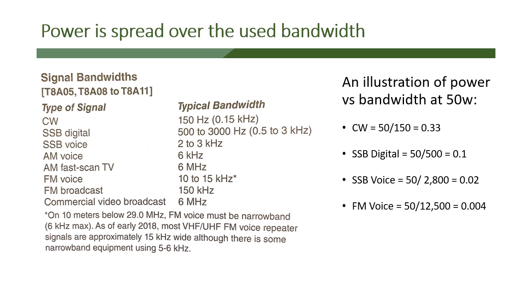Again, these are not the actual numbers, it's just an illustration to show you that as I spread the power, the number of watts I'm going to send out of the antenna, across a wider bandwidth, the average power across that is going to be lower. And that's why, to get the equivalency as the bandwidth shrinks, I'm putting more power per unit bandwidth into that signal. This just gives you an idea of what it's like. And that's why when people want to do Morse code, they're able to go very far with 5 watts or 10 watts, and you're barely making 800 miles with an SSB signal at 100 watts, oftentimes it's because they have a higher power density.